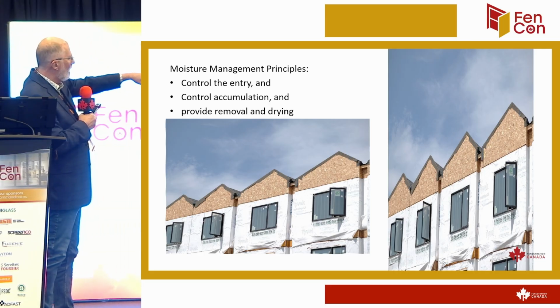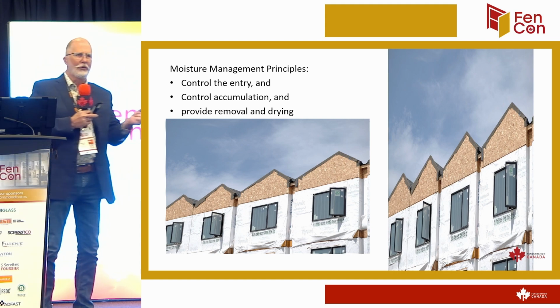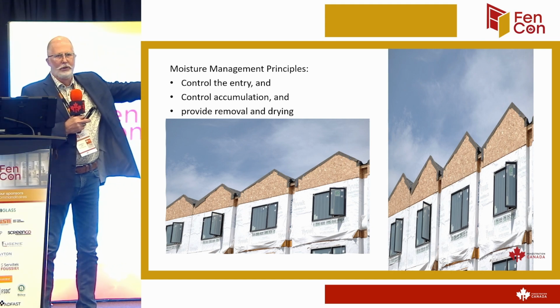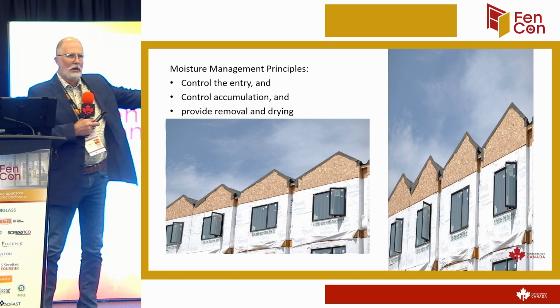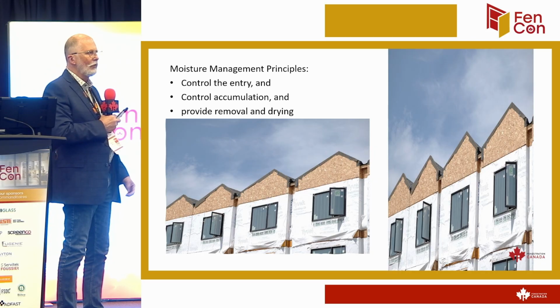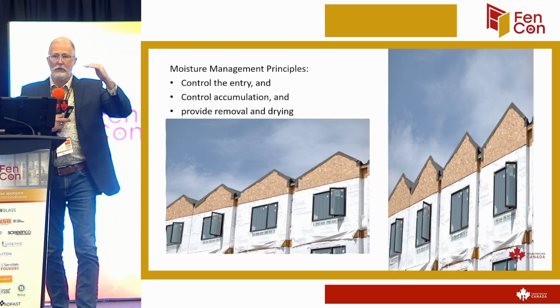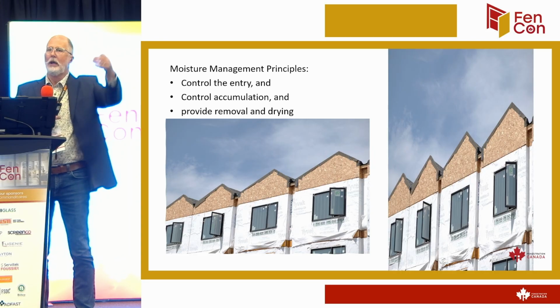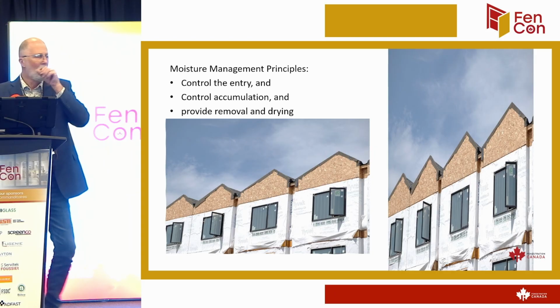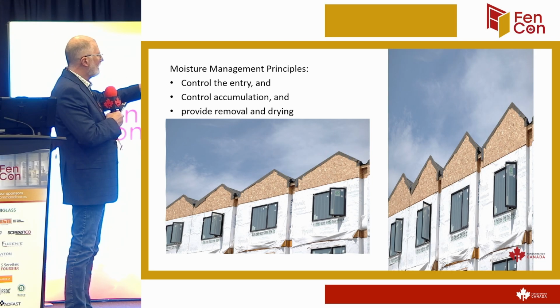If that window on the upper section is completely sealed on the flange, 4 sides, that window will never leak. But what about the window on the next floor down? What about the floor joist space? The water that's running down gets in behind the sheathing, and now it's dripping out the head of the window. So these are some of the challenges when we look at the design.